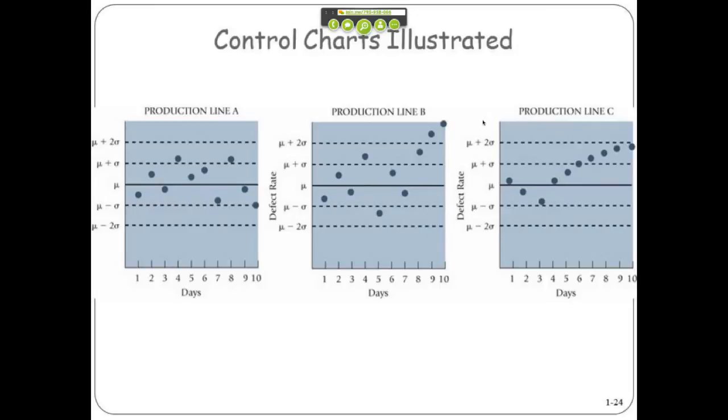In this example, you have what looks like a problem brewing. It was doing pretty well, within a reasonable specification, but towards the end, you started to have some problems. That's a sign that your machines may need recalibrating. And here it looks like there's some kind of a process going on to get the machines right, and you see that you're tending towards a problem area. That would definitely require analysis. So control charts look at some kind of a defect over time to understand where you stand.